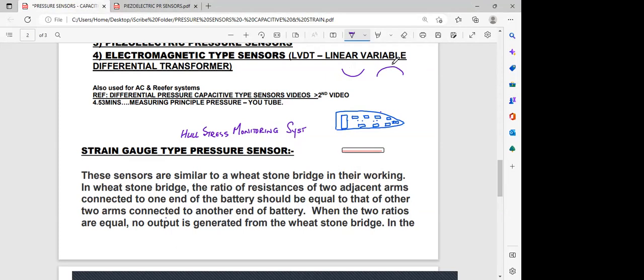upward direction. So especially if you're on a tanker or even a bulk carrier, you have pipes running right from forward to aft. Those pipes are sort of telescopic pipes. And if you're seeing rough weather, then you see those pipes moving in and out of each other. If there were solid pipes going right through, and the ship went through rough weather, then those pipes would rupture. So they are also going to be like telescopic pipes with one moving into the other to allow for this bending